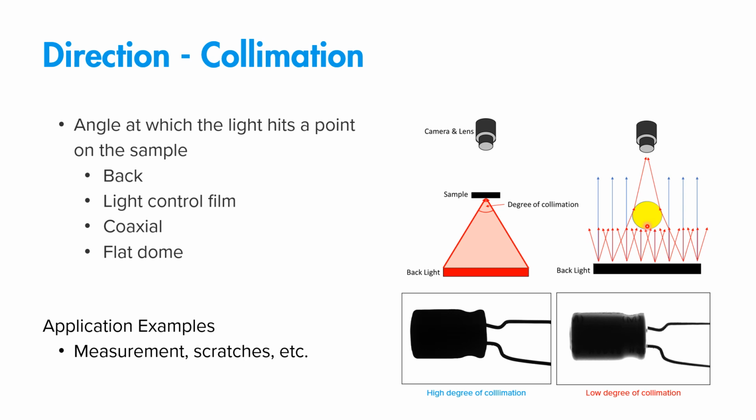And they can come with light control film built in, or it can be an accessory that you add on. And for a lab setting, I definitely recommend opting for the accessory option. That way you have the ability to test the backlight as a standard backlight. You can test and see if the light control film is needed or not, or if even only one direction is needed. Sometimes having just the horizontal light control film is what solves the application, and the vertical one hinders it. So having that flexibility with your backlight is always useful to have.